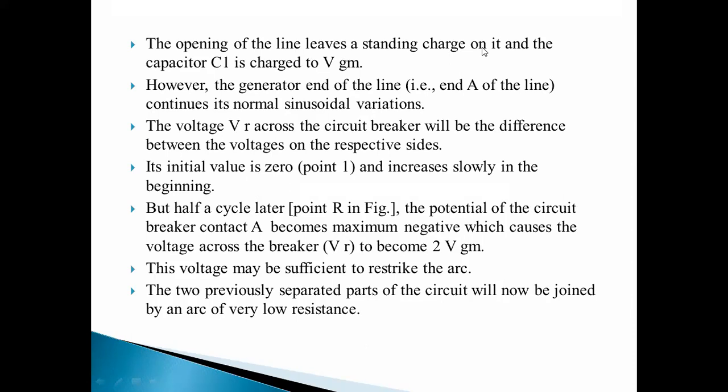And when the line opens, means when the circuit breaker contacts open, that time only your line gets open. It is leaving a standing charge on it, means there will be some charge on that line, and the capacitor C1 is charged to VGM. Okay, so at that time your capacitor C1 will charge to VGM, means to the maximum generator voltage.